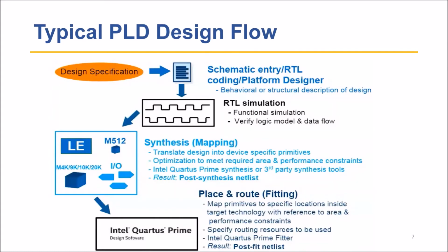The next step is synthesis, that we call mapping in Intel terminology. It translates design into device-specific primitives. It also performs optimization to meet the area and performance constraints.